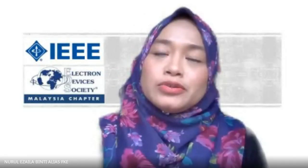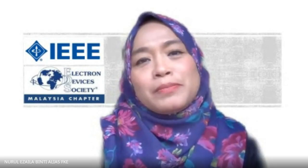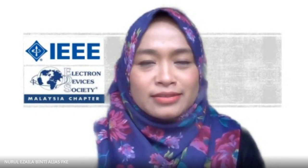Okay. So when you talk about mesh just now, I think we have students here. I think they also need to know this answer. So how do we manage to solve the mesh issue in Silvaco? Do you have any tips on that? So normally for mesh, we just apply a dense mesh on critical areas such as high E-field areas, junction areas, and interface areas. So for our old legacy product, Athena to Atlas, we have one mesh tool we call Dev Editor.